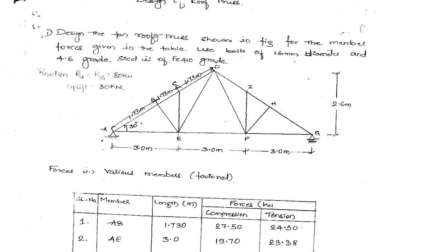Okay, so this is the question that you will come across, and the truss that you see here. Okay, so this diagram will be provided to you, and you should be able to determine the length of each member. Okay, length means we require from one connection to another connection mainly. So that will be the length, unsupported length. Okay, so we'll be taking that itself as effective length here. Whatever lengths are mentioned here will themselves be used as K into L, the effective length in the trusses.